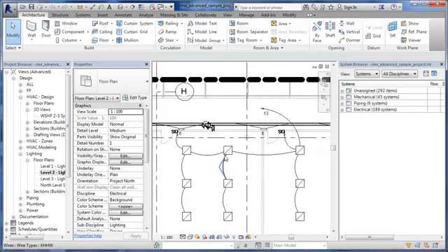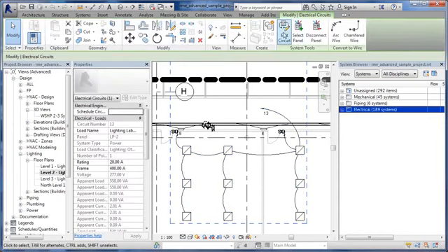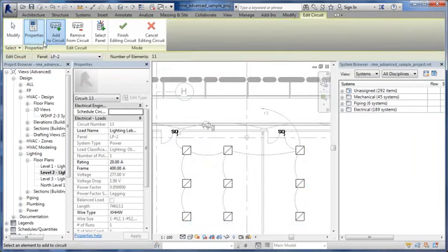Here's an example. I want to get rid of a circuit. Okay, so if I hover over here, I can actually go in and tab to pick the network, tab again, and then click on the whole circuit, and I can say edit circuit. And if I go in and actually remove from circuit and remove everything, okay, it'll delete the circuit, which is quick enough to do.